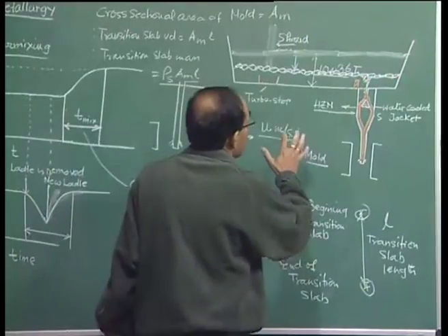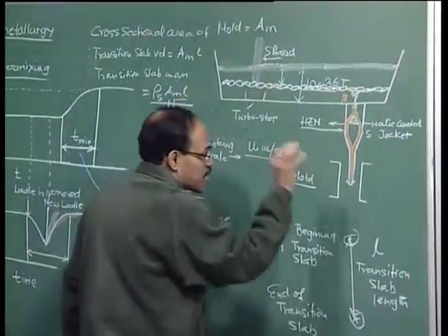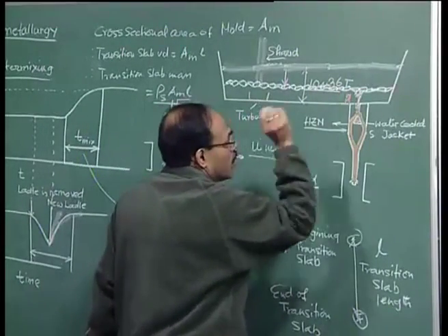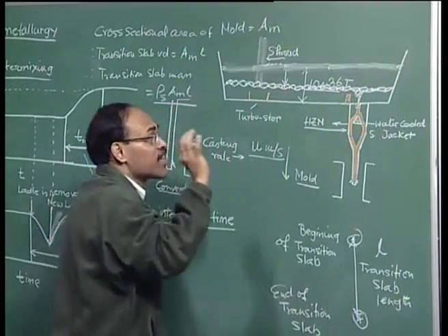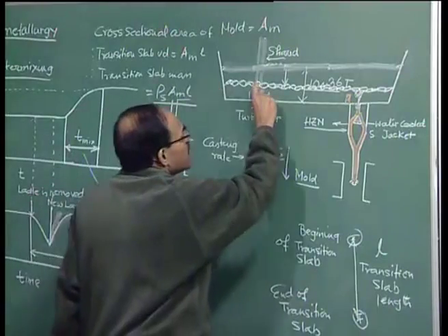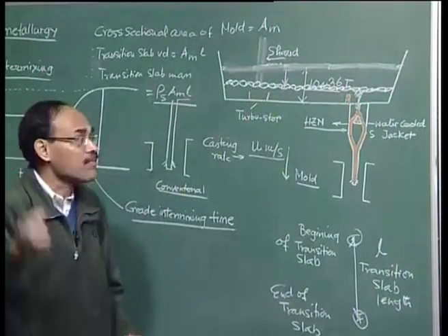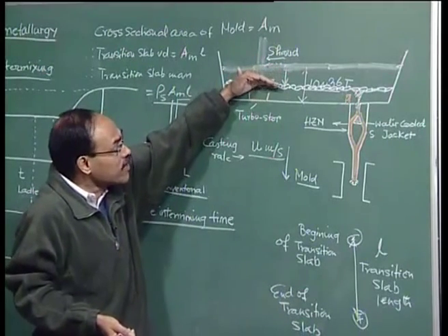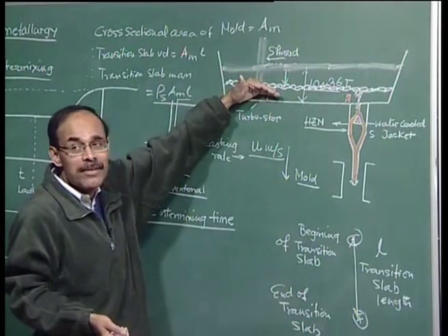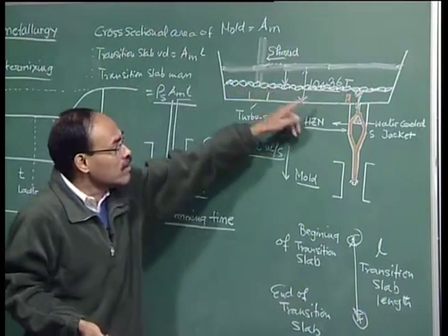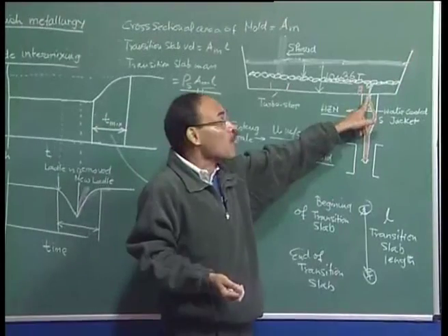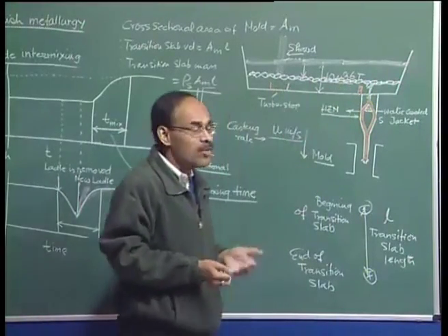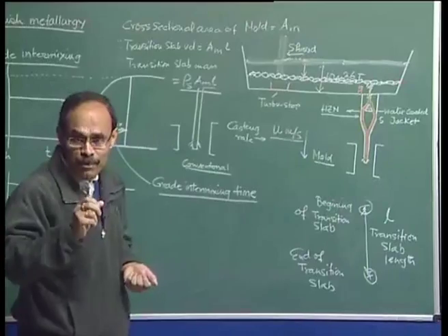But nevertheless, whether it is bloom casting, slab casting, or thin slab casting, you are going to see that some amount of funnel vortexing is going to generate at some instant of time, when there may be still 5 tons or 7 tons of material left. So, we have started from 36 tons of material in a slab caster, and by the time the material falls to about 5 to 7 tons, an intense funnel vortex can form, which can entrain the deleterious upper phase slag into the mold. It is at that instant of time that the casting has to be stopped.